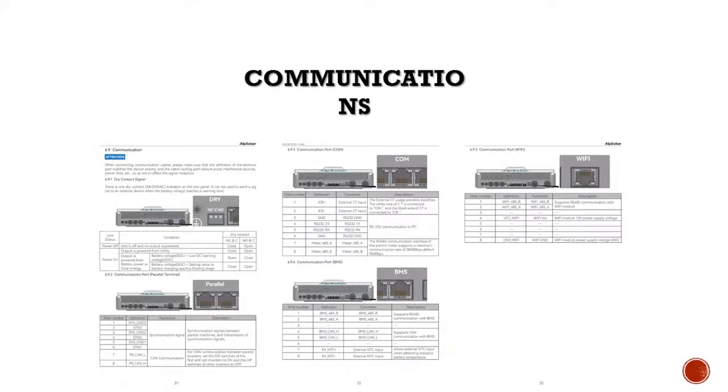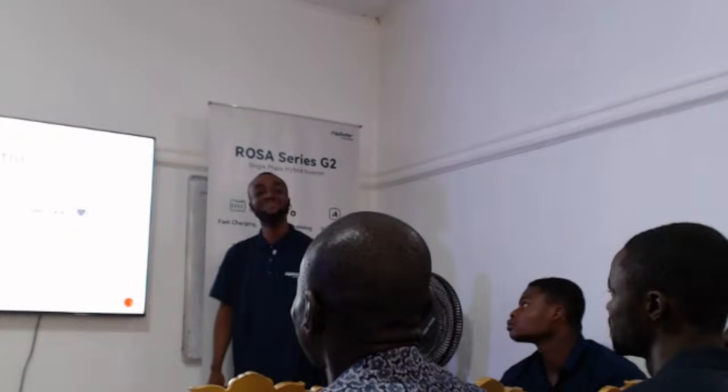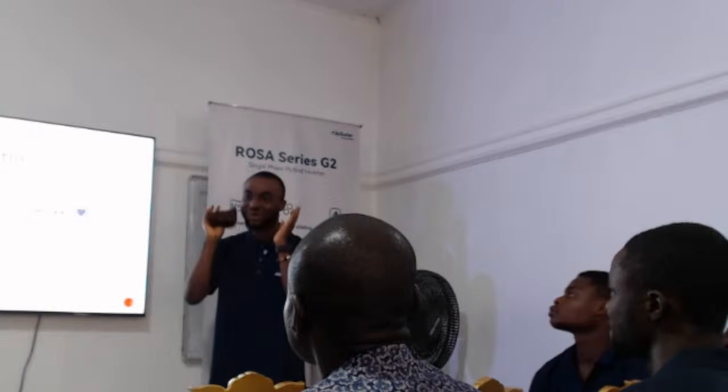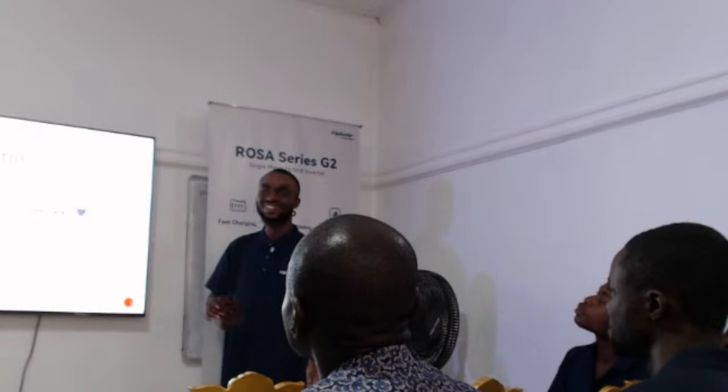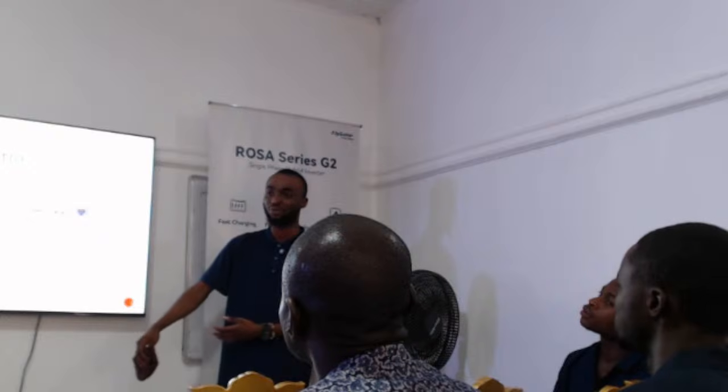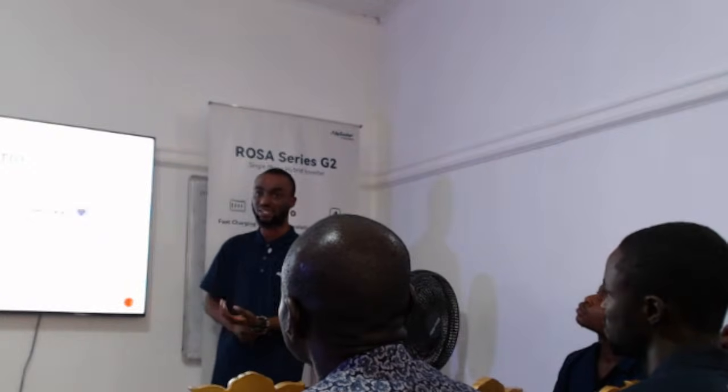The old Felicity battery could only communicate with its own inverter. But thank God, their new battery brands have a separate CAN port, and we have communicated it with our inverter, and it works perfectly fine. So if it has a separate CAN port, it will work perfectly fine.